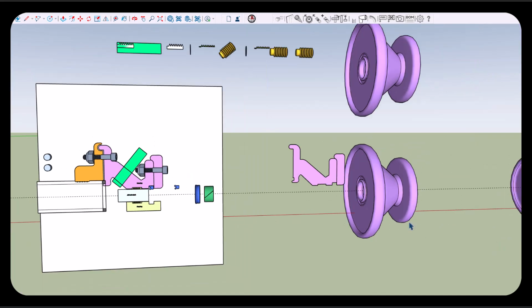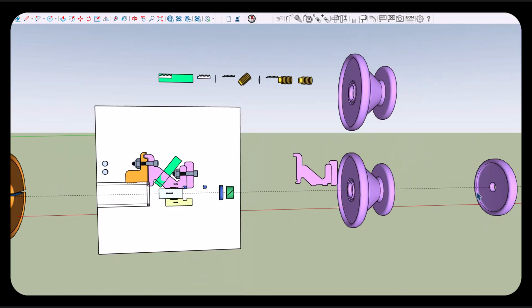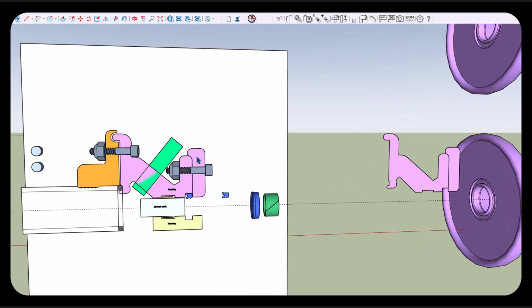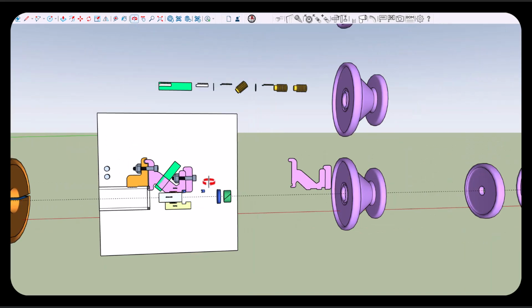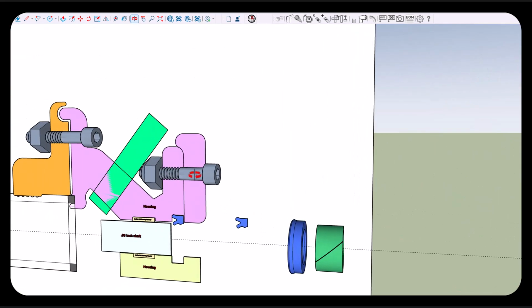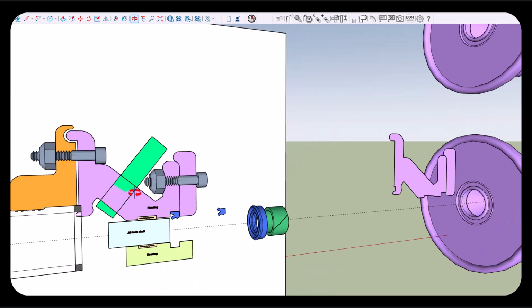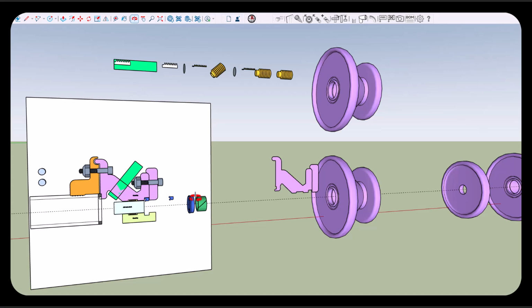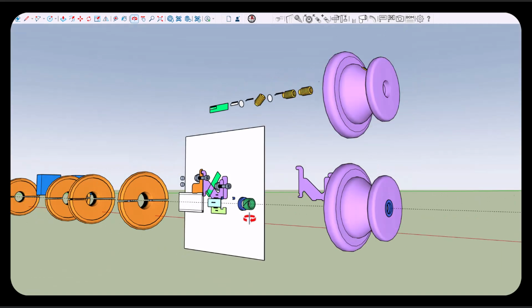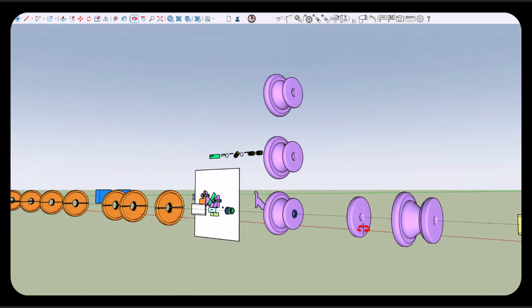So we took this cap right here and pulled it up against that, and it will have in it these brass socket head bolts with the nylon insert stainless steel locking nuts, and they pull this cap against this surface. And I haven't shown them, but they go here. There's maybe 6 of those there.